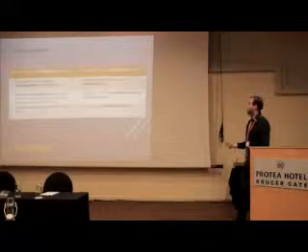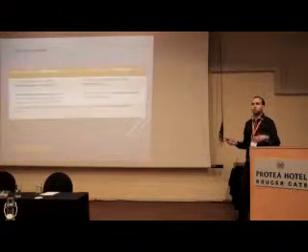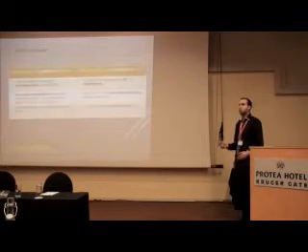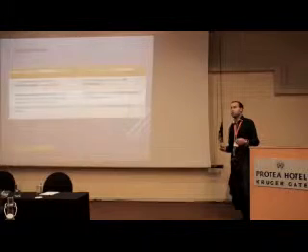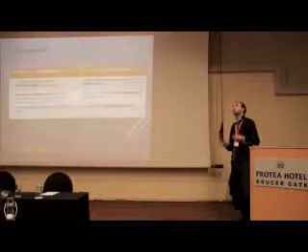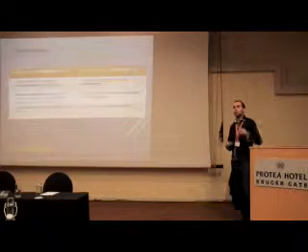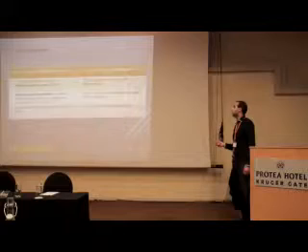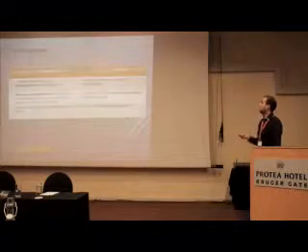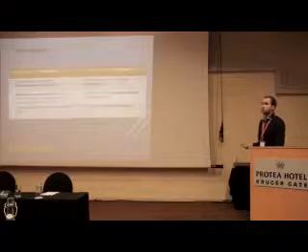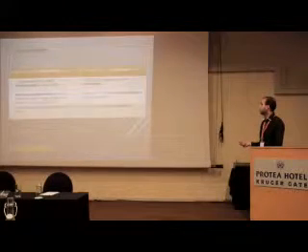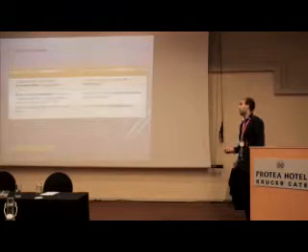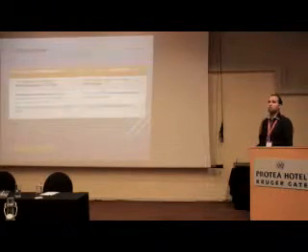Maturity. This Zedboard, this FPGA, includes AES and SHA function algorithms, but it's very hard to program that in VHDL. So you have to first compile or use another language, like Verilog and VHDL, to do that. And the last disadvantage is the overall cost. The board I'm working on is about $1,300 for the full system on chip, which is, I think, bad for doing software-defined radio for this project.